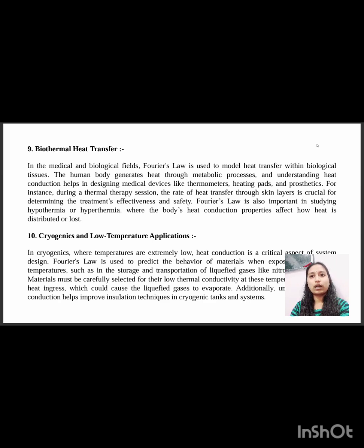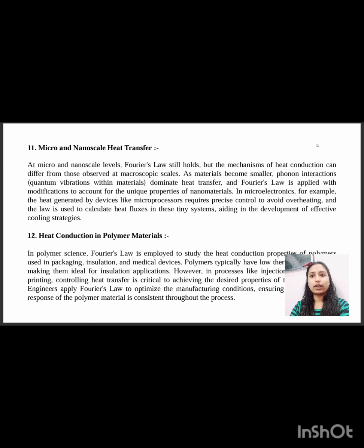11th one, micro and nanoscale heat transfer. At micro and nanoscale level, Fourier's law still holds, but the mechanism of heat conduction can differ from those observed at macroscopic scale. As materials become smaller, phonon interactions and quantum vibrations within materials dominate heat transfer, and Fourier's law is applied with modification to account for the unique properties of nanomaterials in microelectronics.